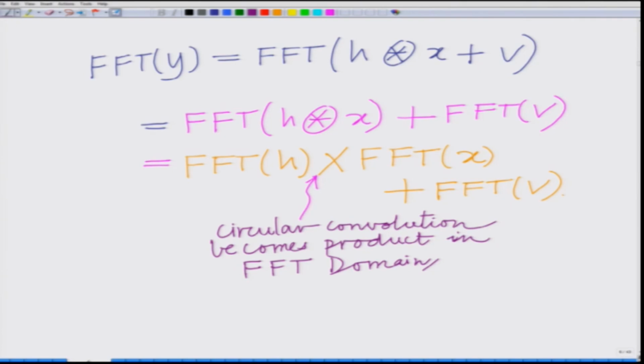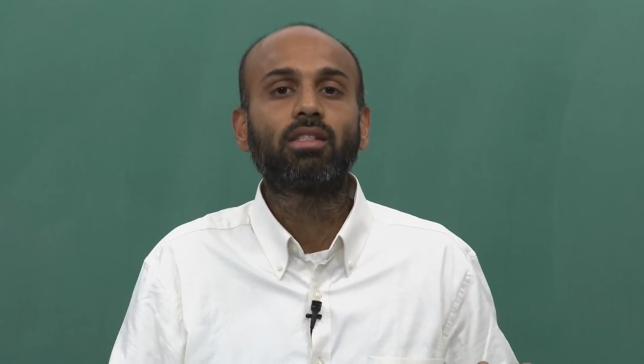Alright. So, that is the interesting aspect of OFDM, where we have taken a block of symbols, capital X0, capital X1, capital X2, capital X3, performed the IFFT, or the IDFT, to generate the samples. To the samples we have added the cyclic prefix, and now once you look at the output of the intersymbol interference channel, you see that what the channel is performing is equivalent to a circular convolution.